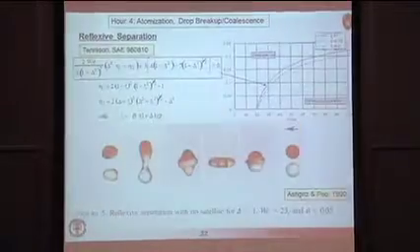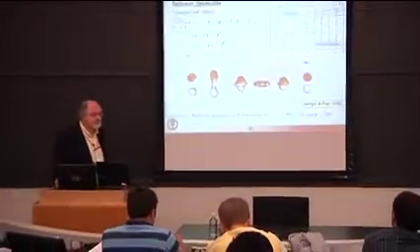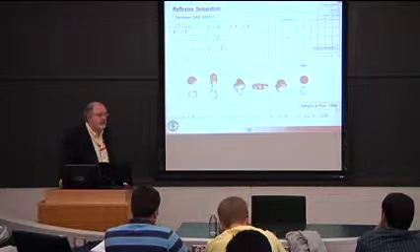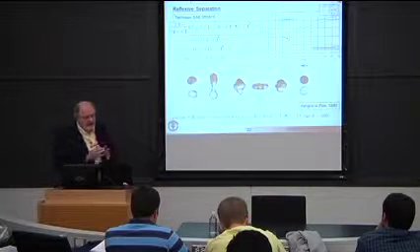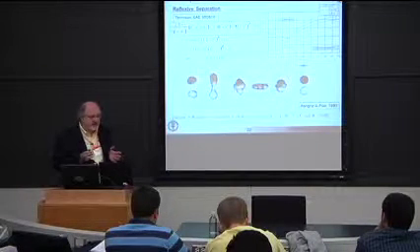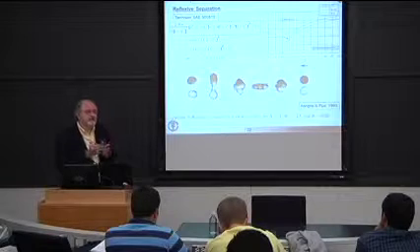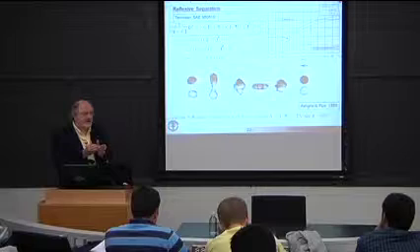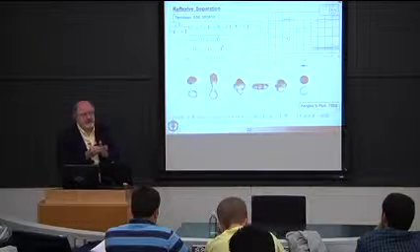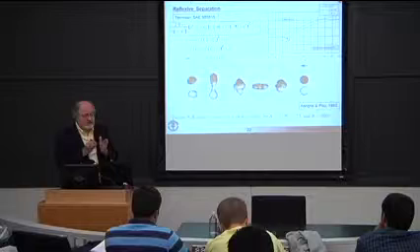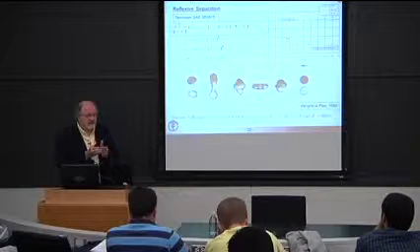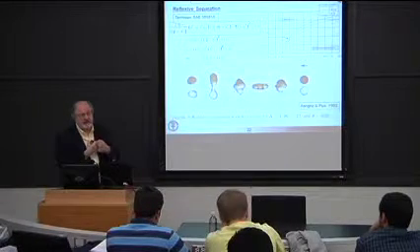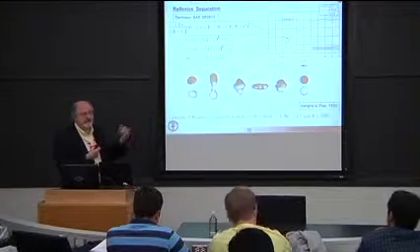So you're tracking each parcel, and then whenever two parcels come close enough together, at that point they're assigned a random impact parameter? Right. So actually we do it this way. We found that the results of these collision models can be very sensitive to the mesh size. If you say that I'm just going to look at the droplets in a particular computational cell, which is the original formulation that O'Rourke had, so if you just say, I'm going to take the drops in a computational cell, decide whether they're going to collide, calculate a collision frequency, and then for those that collided, see whether they coalesce or break up and so on.